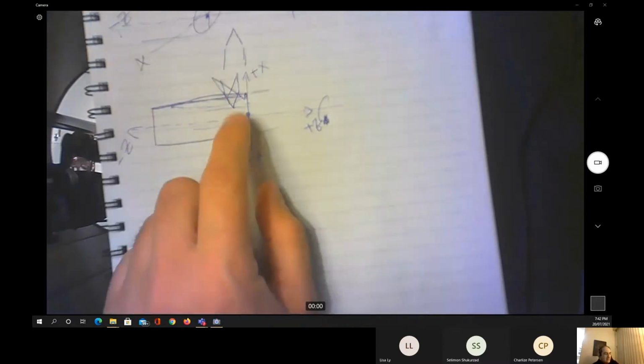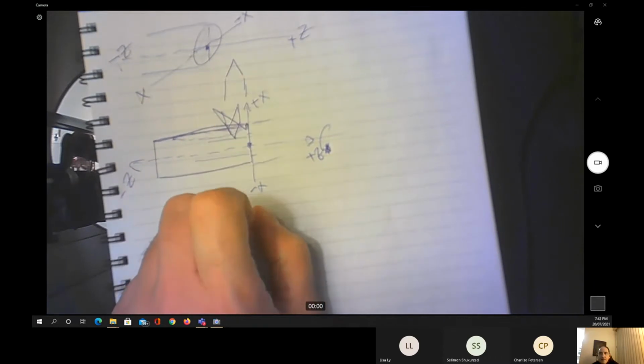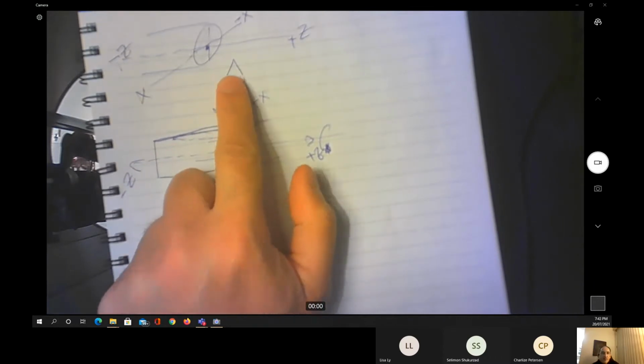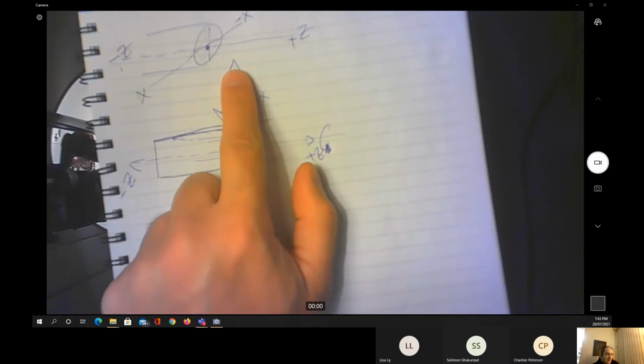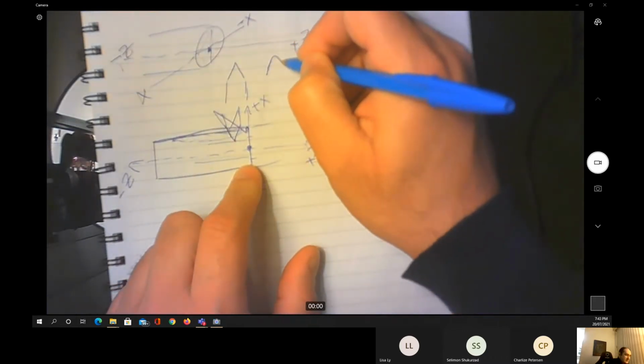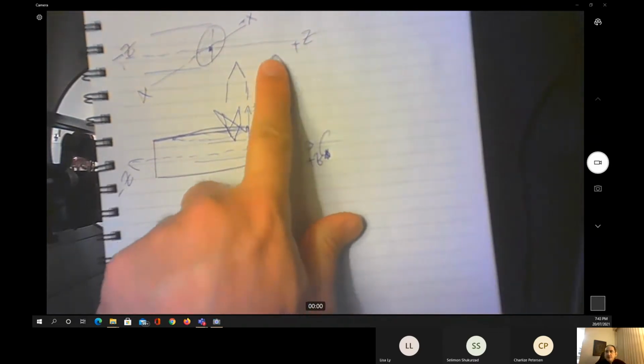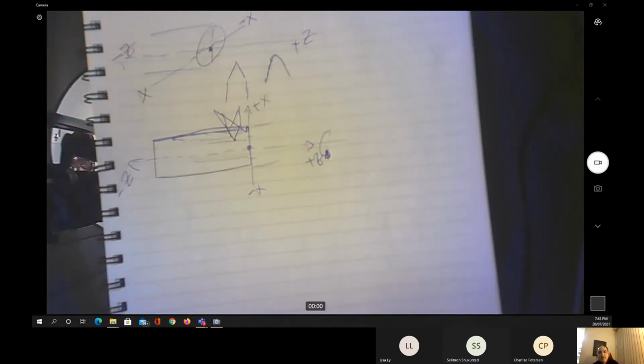The second thing we have is that usually in the case of the cutting tool we have in the turning operation, if it's going to be high-speed steel, it's going to have a sharp nose. If I'm going to have the carbide insert, it's going to have a round nose. Like that. And the round nose is going to be very small, actually. We have to do the compensation for the radius. That means we need to do the cut at a certain offset.